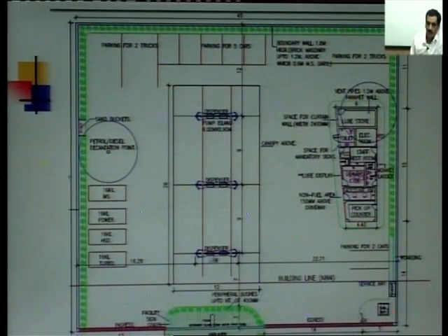In other words, we can't use GI pipes. GI is the galvanized iron pipe. It is CI, cast iron pipe, because GI pipe has more conductivity, and in that case we can land into more troubles, and there are chances of fire.